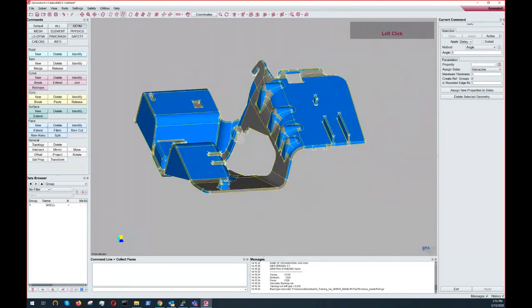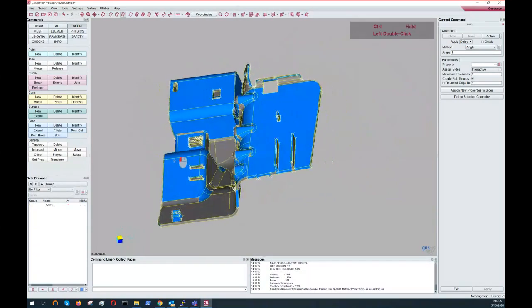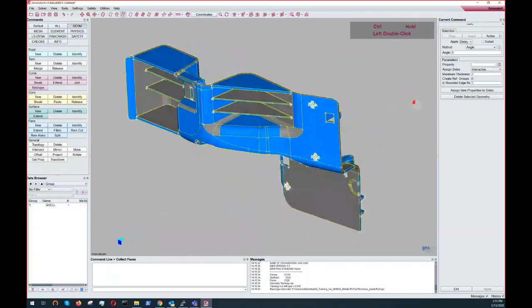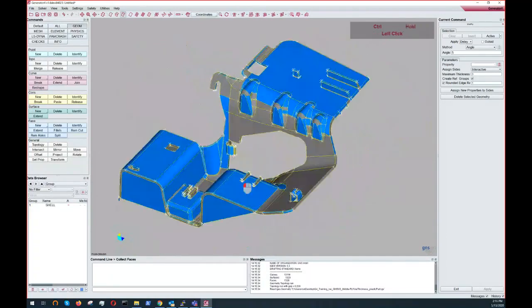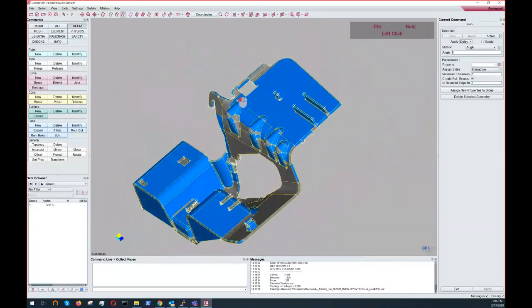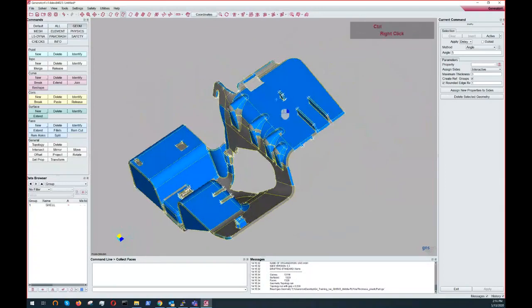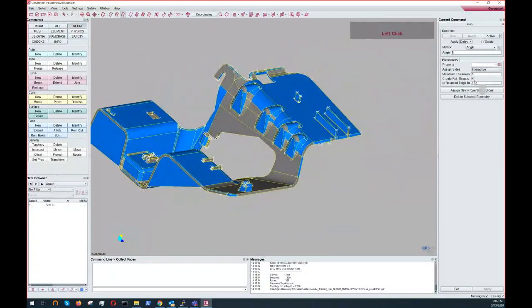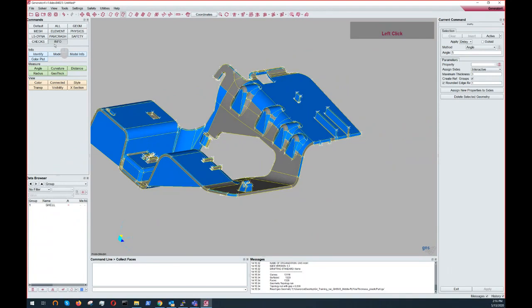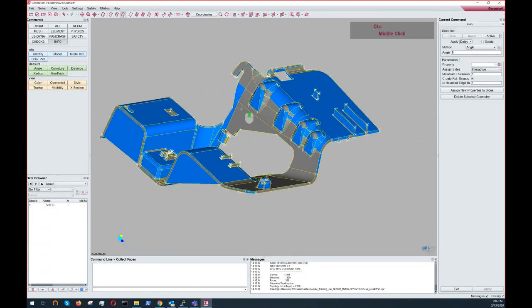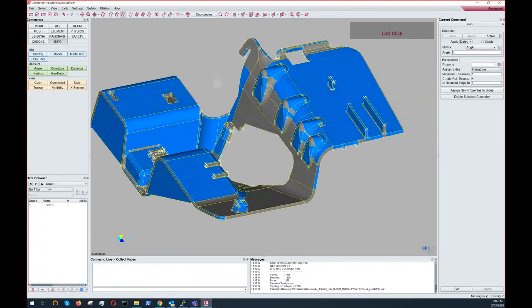These are working good for the majority of the geometries we have been testing and the most common ones. But maybe if you have a different one or just really thin volume or whatever, maybe it's worth it to adapt these values. And how to get meaningful values for this? One can always go to the info area here, the command group, and evaluate a little bit the geometry you are working on before you attempt to create the middle ply.